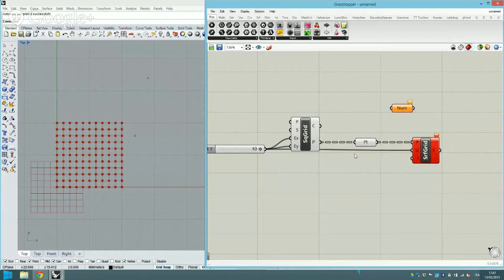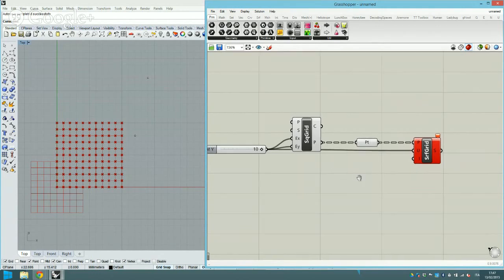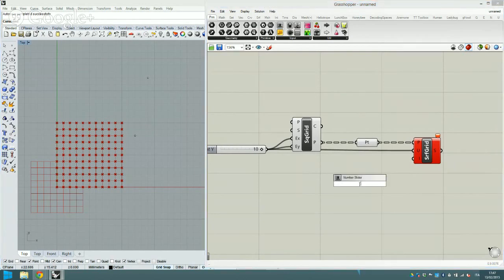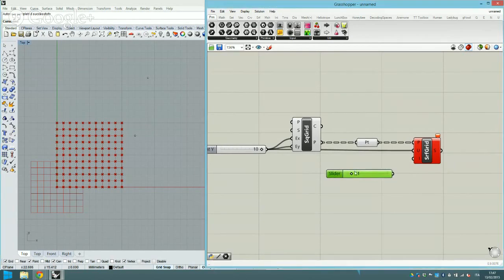So it's empty, it's with information working properly, and it's gray, and it has an error, and the color turns to red. Okay, why is there a problem here? Because basically we are saying that the subdivision is 10, but as I told you before, since Grasshopper starts from the number 0, we have to add another number. So we can do this. We can type 11, and once you type 11, you already have a slider with the value of 11.